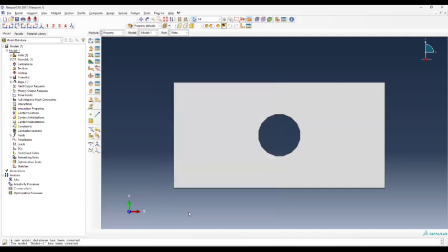We hit OK. Now we create a section. So it's going to be a solid, obviously, a homogeneous solid, which I'm just going to call the plate section. Continue. And I'm going to assign it to the steel material. Is everyone following up until this point, by the way? So steel section, homogeneous, we assign that. I do material steel, okay, we're all good here.